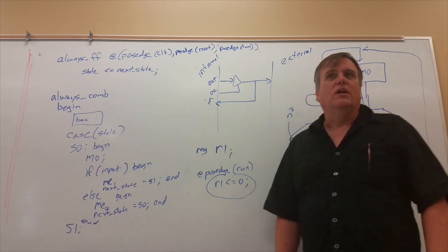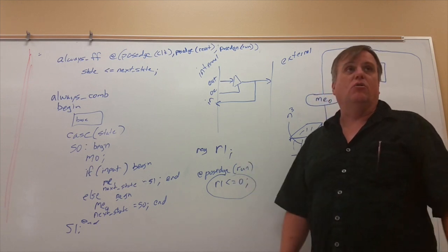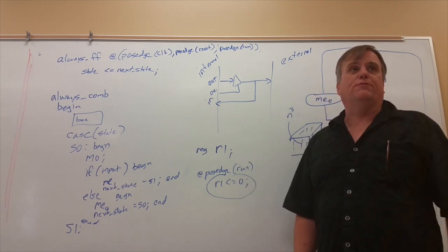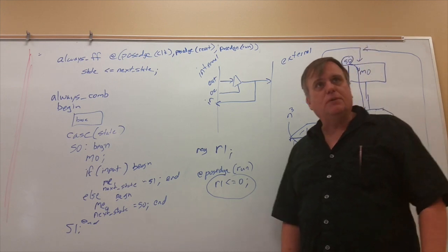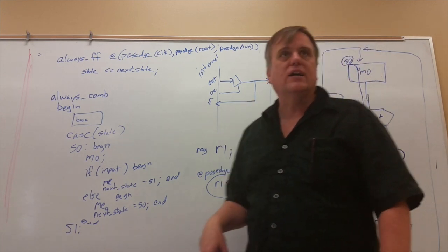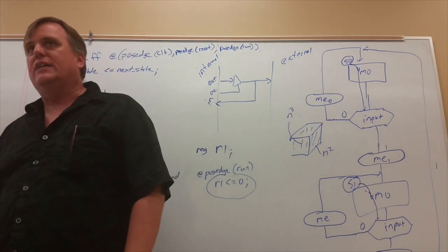So, in general, if you're setting it to 0, I would assume it would generically be most likely an asynchronous clear at start. And there is typically a startup flag, like a run flag. And that run flag is probably going to do an asynchronous clear.